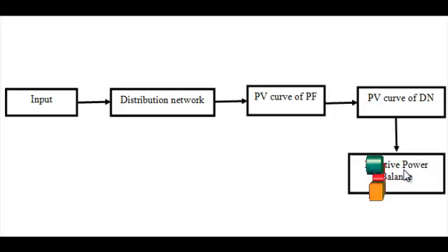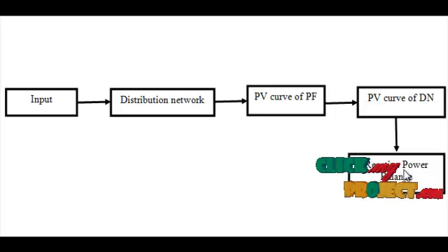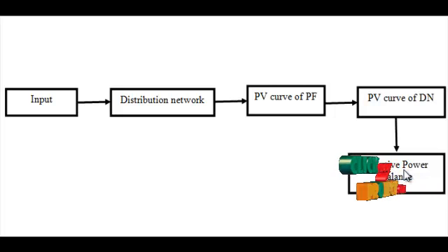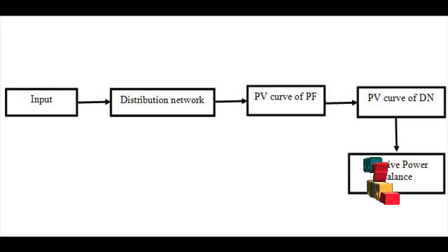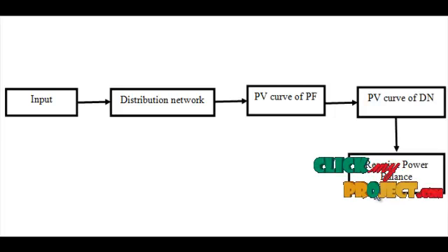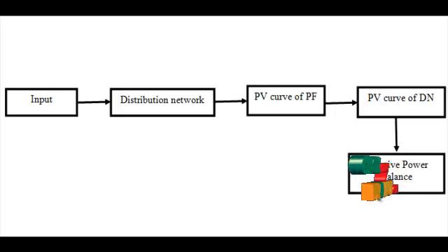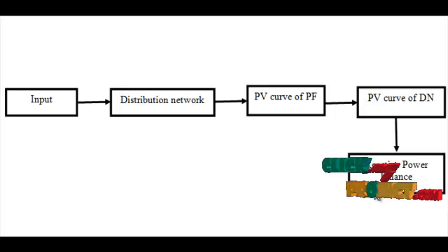Assuming that the power grid voltage V0 is 1.1, four grid reactive power voltage curves are drawn with various ratios of reactive power with respect to active power. The family of curves is drawn together with the load reactive power voltage curve. The load reactive power voltage characteristic is described by a quadratic curve. The curve characteristic parameters are as follows: the rated voltage Vn equals 1, the critical voltage Vcr equals 0.75, the rated reactive power Qn equals 0.2, and the absolute value of dQ by dV in the left section is 2 times bigger than that in the right section.